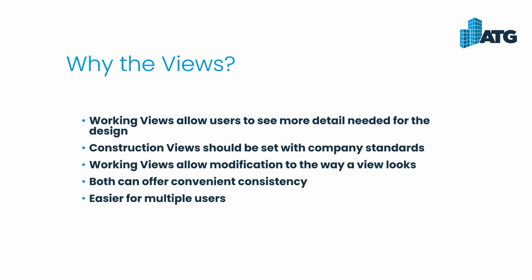I always tell people when I talk to them about view templates in a class, always have a view template assigned to any view that is going to be placed onto a sheet. That means all your construction views should have a view template assigned to them. That way, you know you've got that standard set up within not only the company, but the Revit template there.